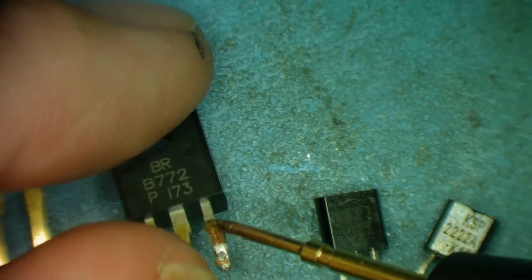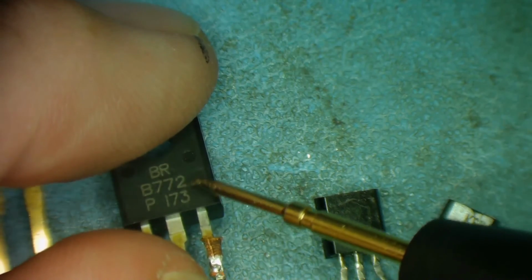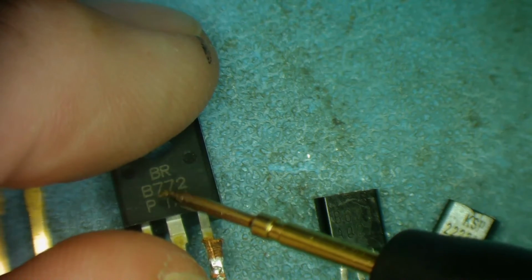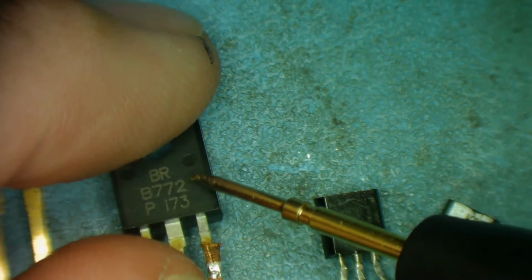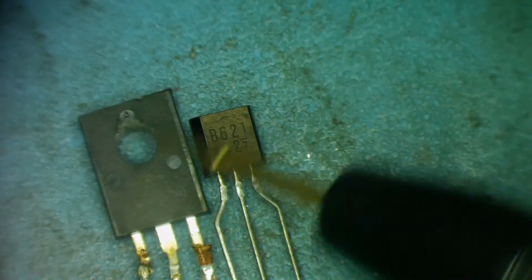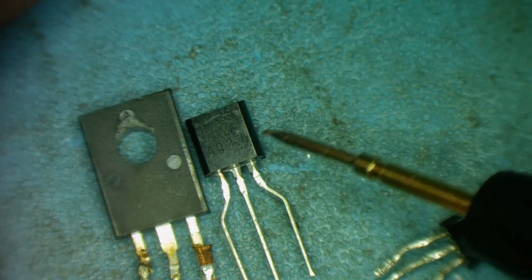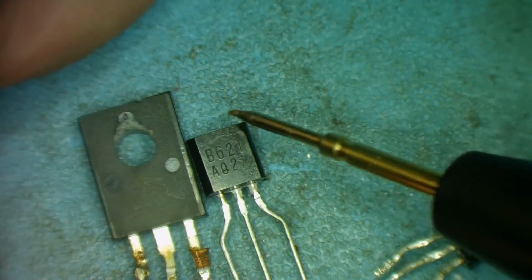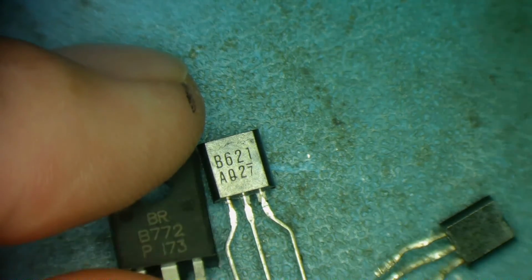You'll also find a lot of transistors that are marked A, B, C or D, like B772, C3011 or A2478. These are a Japanese method of numbering transistors, and you'll often find that in front of the letter on the data sheet is 2S.